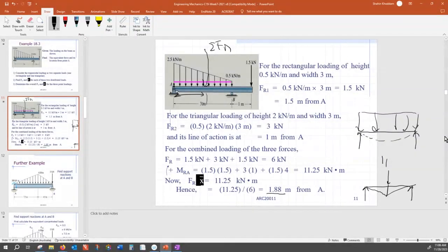So that is why the simplification is not for calculating the internal forces or the deformation. The simplification is only to find these two reactions. Once you find the reactions, you roll this back to where it was. So later on, when we are trying to find the internal forces, we can't use the simplified free body diagram. This is only a simplification for finding the reaction.